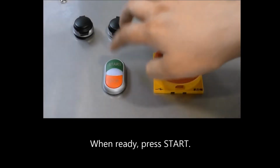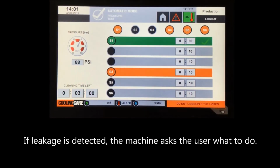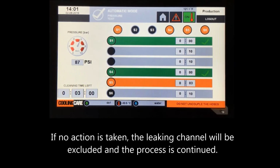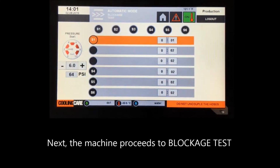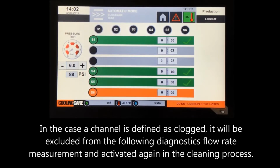When ready, press Start. The machine begins with the pressure test, verifying if there is no leakage. If leakage is detected, the machine asks the user what to do. If no action is taken, the leaking channel will be excluded and the process is continued. Next, the machine proceeds to blockage test. In the case a channel is defined as clogged, it will be excluded from the following diagnostics flow rate measurement and activated again in the cleaning process.